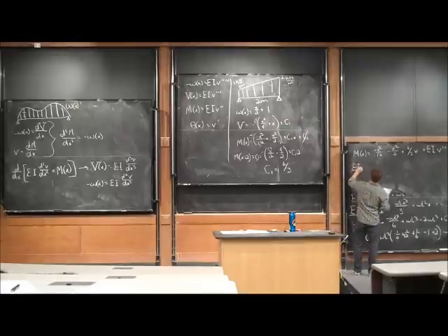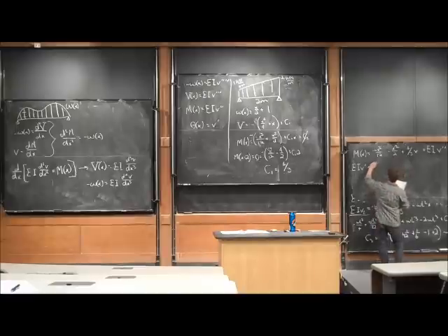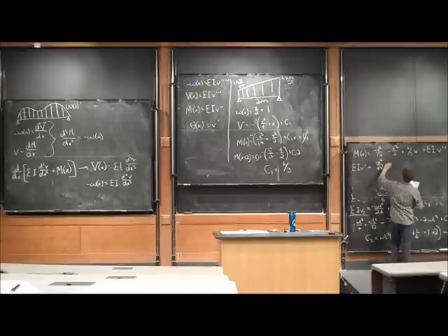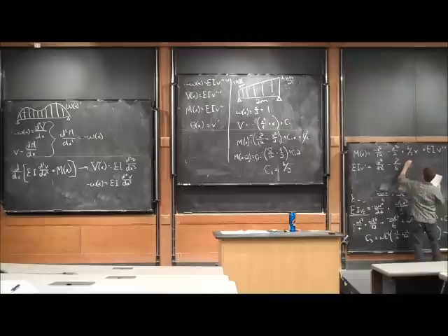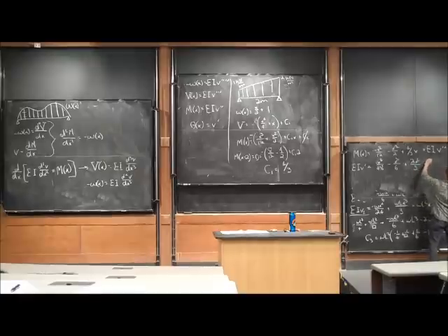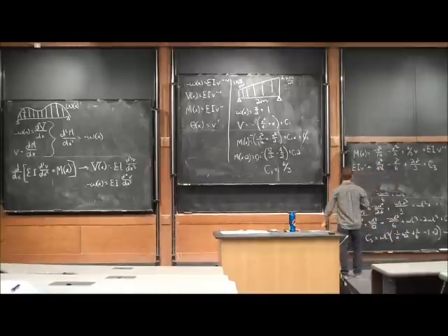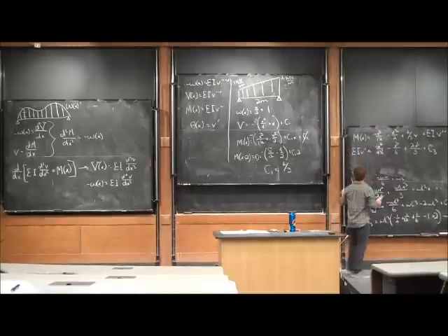So I can now integrate that to figure out what my rotation angle equation is. My rotation angle equation becomes negative x to the 4th over 48 minus x cubed over 6 plus 2x squared over 3 plus C3. I can then keep going and integrate it one more time.